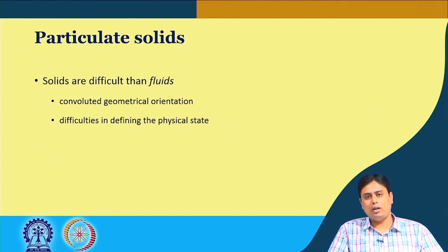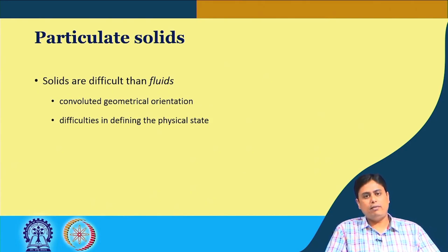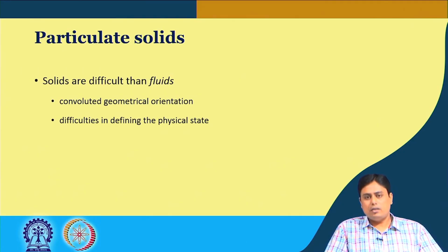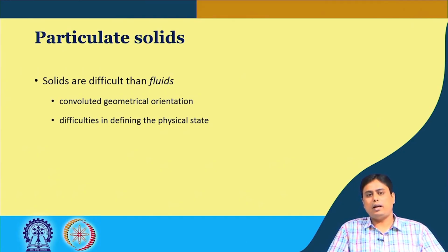and in fact those perceptions are sometimes counterintuitive. For example, to mix two liquids, what do you do? You take those two liquids, put them in a bucket, and then vigorously mix them. If you do that for solids, if you take different types of solid particles, mix them in a container and shake, stir or vibrate it vigorously, what will happen is particle agglomeration or particle size separation instead of the mixing that happens in the liquid or gas case.